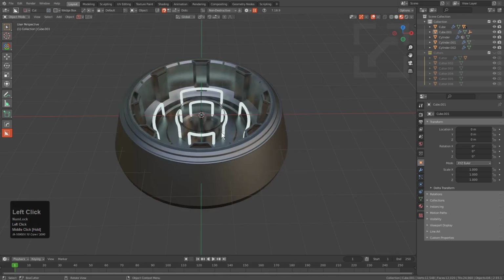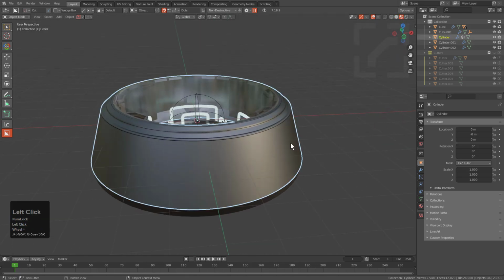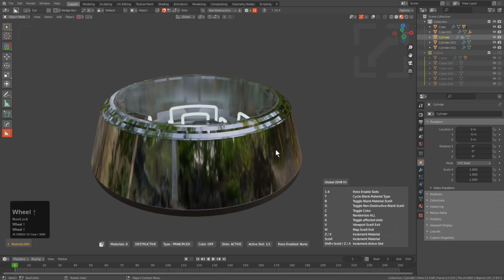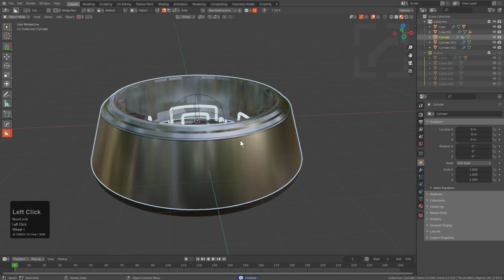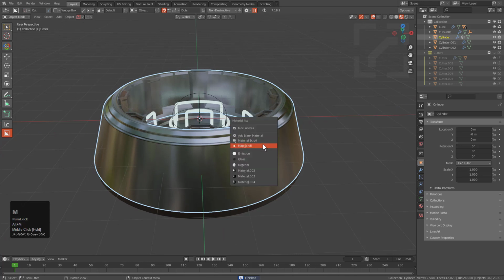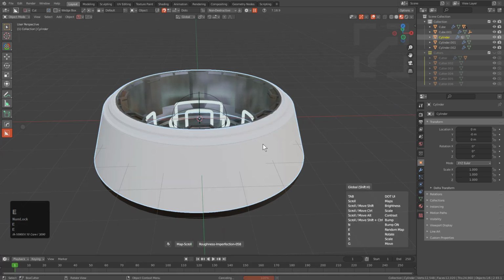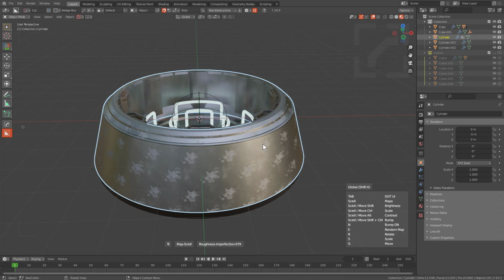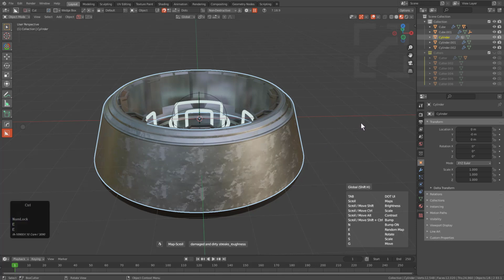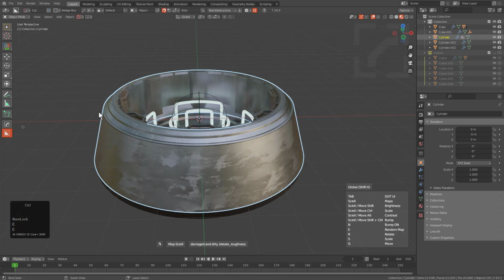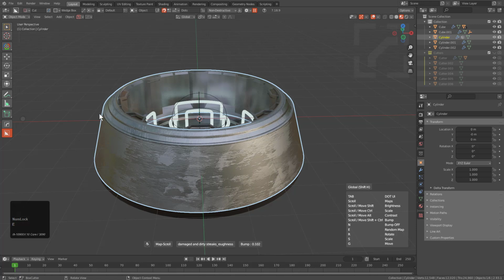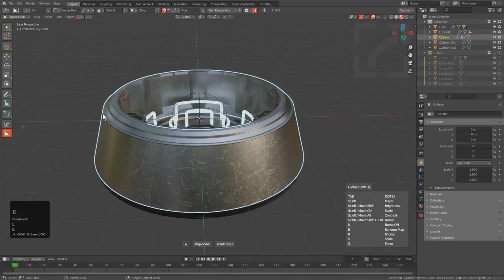However, if we jump over to our render, we could see kind of what our render materials gave us. So for this object, we could just Shift click on material scroll in order to scroll through other iterations of a different material that could have been. And so with something like this, we could then go back in, play with our map scroll, press E a couple of times to just bring up random maps until we find one that really suits this particular surface. And we may even want to hold Control and move our mouse in order to adjust our scale in the 3D view. Hold Control Shift, maybe affect the normal just slightly. We can still press N or E actually to jump to random images until we find just a perfect image.